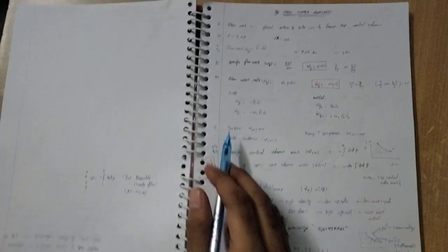The outlet is also there. For a turbine the control volume work is positive, but for boiler and condenser the work done of the control volume is generally 0, meaning we don't get any work there. For the next one, pump and compressor, the work done of the control volume is negative, which means they are power consuming devices. So the specific control volume work is W_CV equal to minus the integral from inlet to outlet of specific volume v dP.